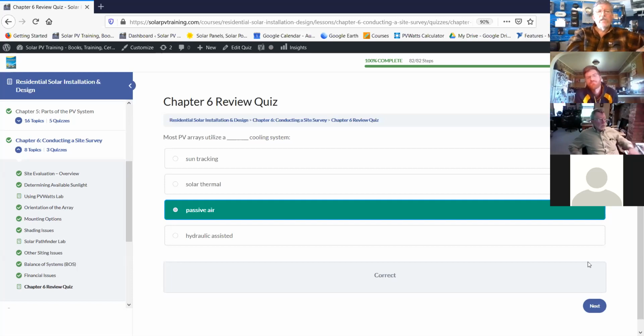So don't try a do-it-yourselfer with flashing, because that's not going to be the right solution. There are some experiments with cooling with water. That's a nice option, where you could run streams of water over the panels or in the panels, and then use the heat to heat the water, as a secondary hot water source. Those are interesting, but again, now you've got water and pumping, and water and electricity sometimes have a difficult relationship. So you'd want to make sure that everything is properly insulated and sealed.